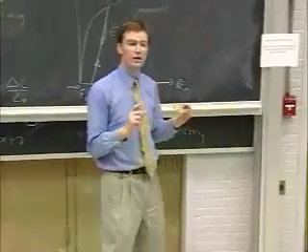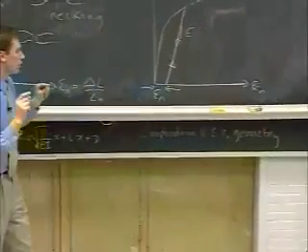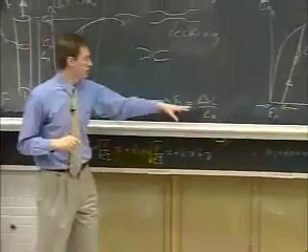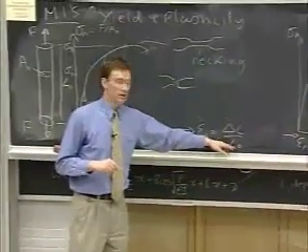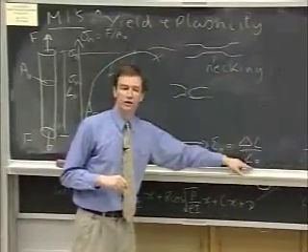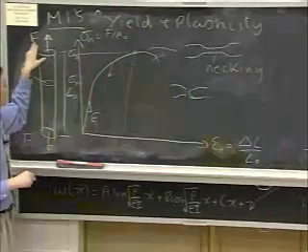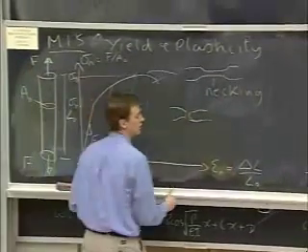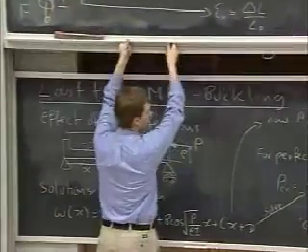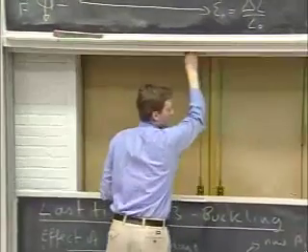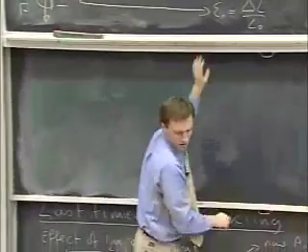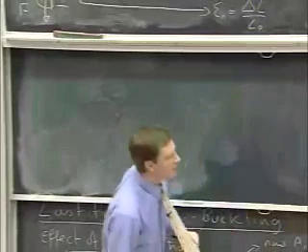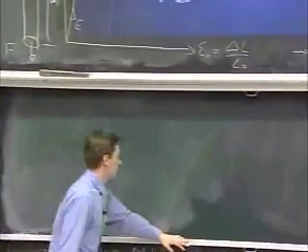So we have to be a little bit careful about how we define our reference for the length. Just plotting delta L over L0, and for that matter, stress in terms of force over area, is not quite enough. So the way we deal with this is to refine our definition of strain.